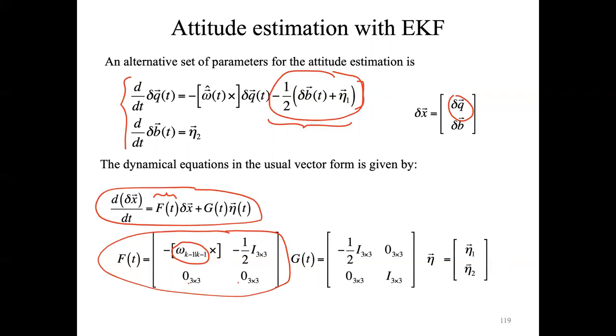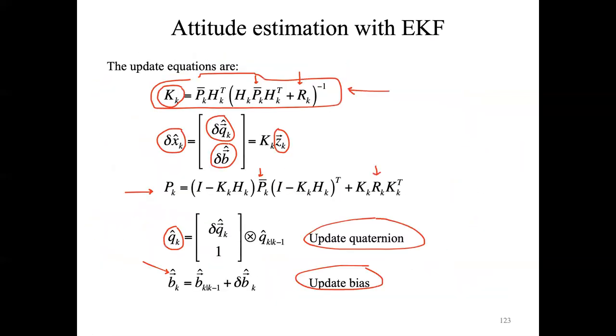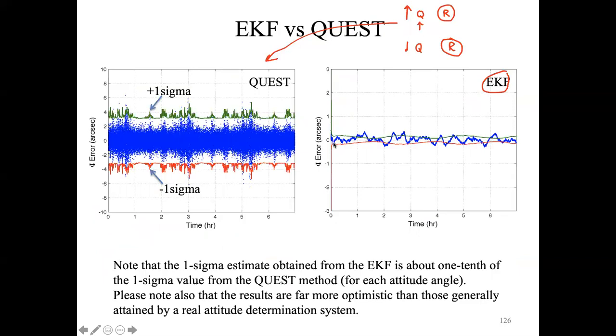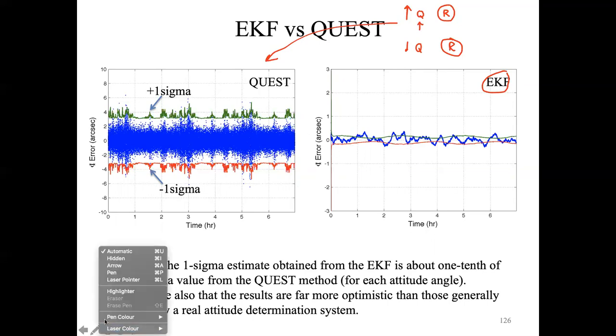This assumption is approximately consistent, and for example, one of the observations from the person who asked the question was whether that assumption depends on the time integration of your observation. Looking at the plot of this solution, you can see that you have a fair amount of observations every second. If you have one observation every, for example, 10, 100 seconds, you are not able to track the variation of the bias of the gyroscope with a refined time step. So you're going to lose the information of the time variation of the drift. In that case, that formulation probably is not fully adequate.